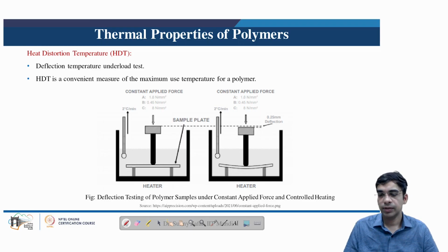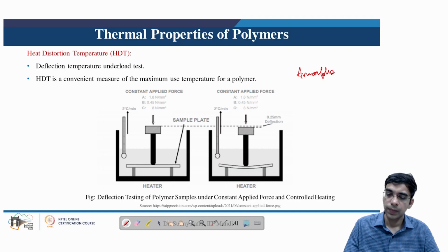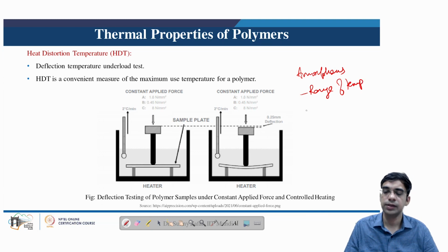Another challenge is because of this amorphous nature, you have a range of temperature over which the polymer is basically functioning or the polymer is melting. Secondly, the polymer mechanical properties are also dependent on the rate of loading.